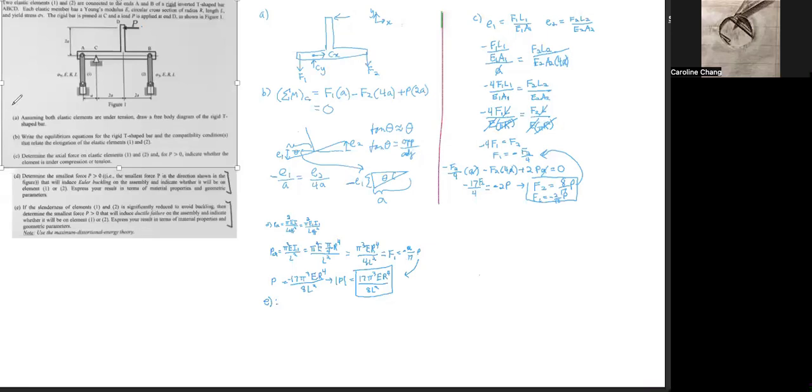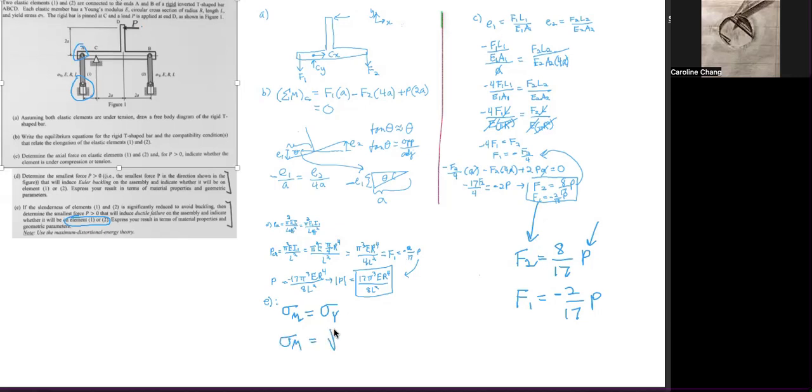So first, notice that this is an axial system. We're going to write our equation first for the von Mises stress. So sigma m is equal to the square root of principal stress 1 squared plus principal stress 1 times principal stress 2 plus principal stress 2 squared.